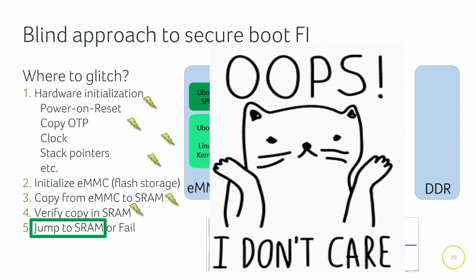Of course, this is an approach that might work in some embedded systems, but it is like playing the lottery or finding the needle in a huge haystack. The chances of succeeding in a modern system just by a blind approach of glitching are not that great, because bootloaders which implement secure boot strategies take quite some time to boot. So we have many times to inject this glitch.